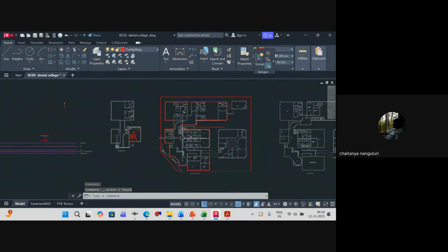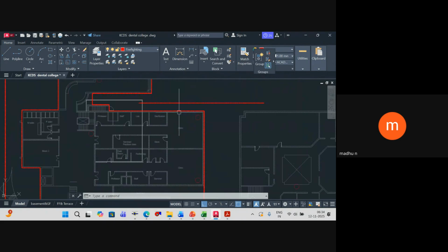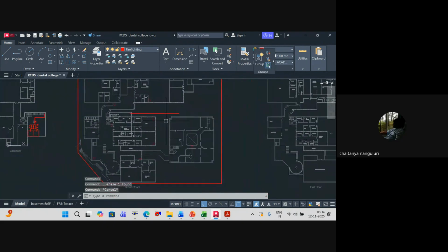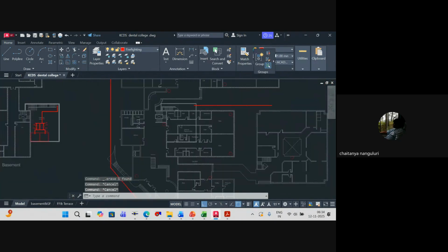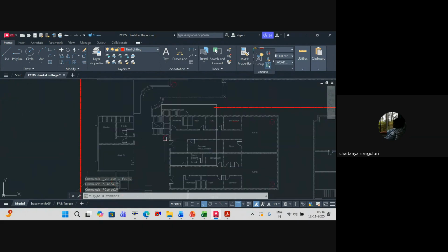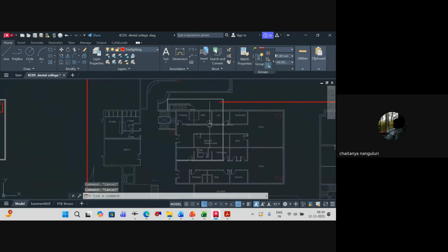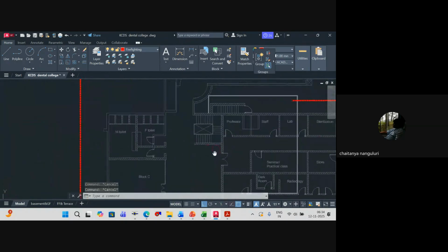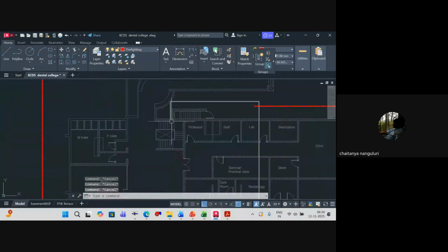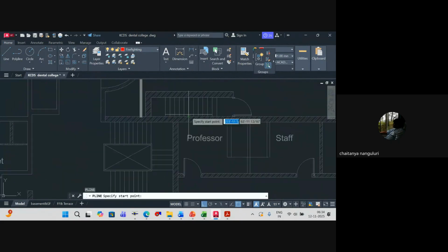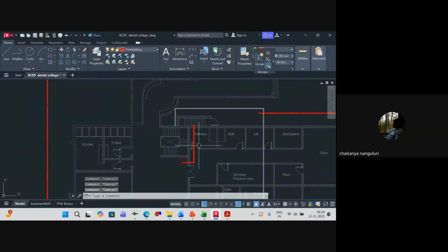So if I have 2 zones of sprinklers and this independent building, I'll take it as a separate zone. So at least 3 zones I'll have. Let's take, for example, one sprinkler pipe, or one hydrant valve, I've given from this location. In that case, if we want to do it over here, one piping I'll connect from here to here. From the external ring main, I have to connect it somehow or the other.